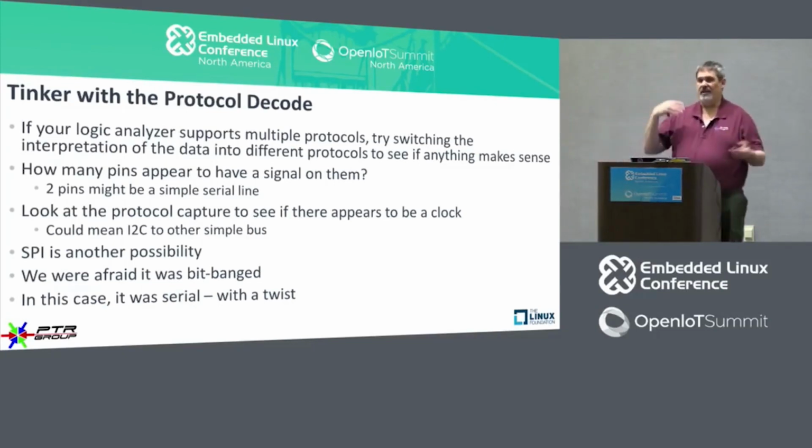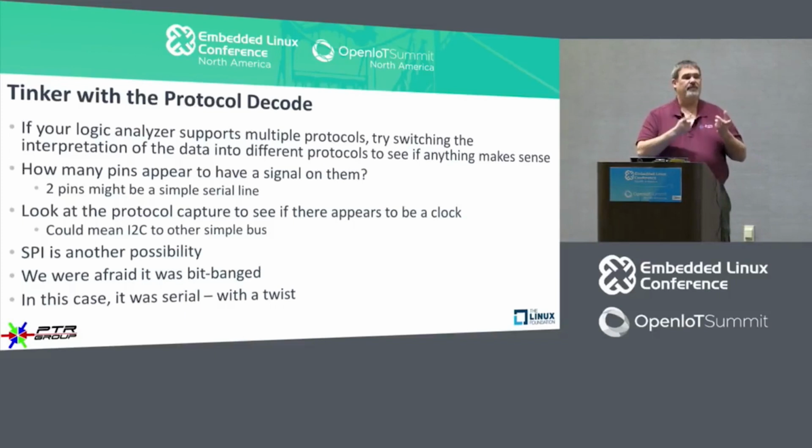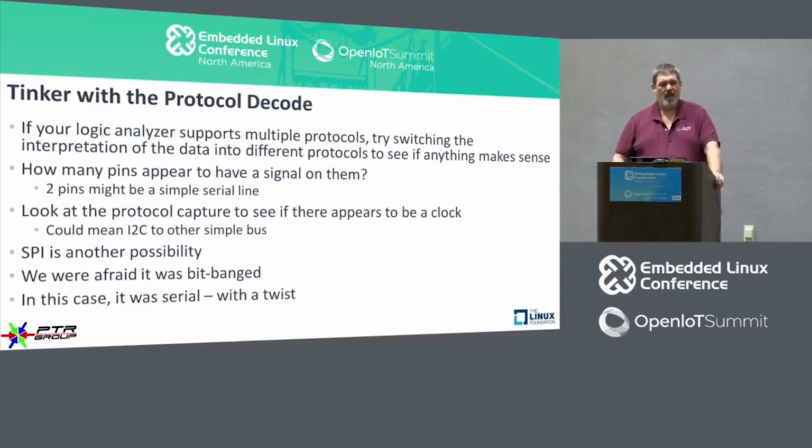You'll figure out what the I2C ID is, and little tools like Arduinos are wonderful at being able to decode this kind of stuff. Generate the actual I2C clocks, the SPI clocks, and then be able to get the device to talk to you, even though it's maybe kind of isolated from the rest of the circuitry.